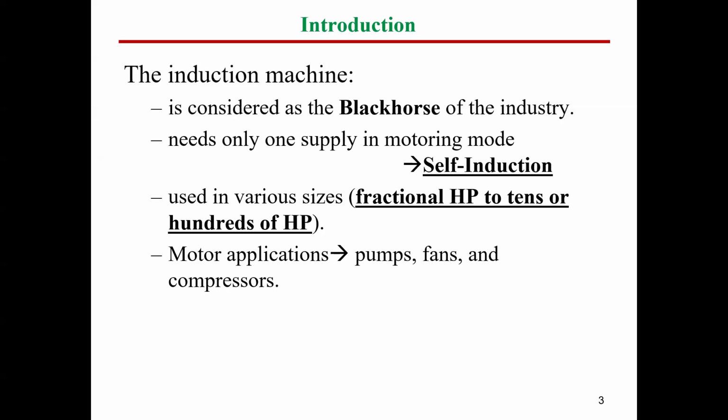So we will draw the torque speed characteristic and see the load and motor characteristic. For the fan load, all of these types of loads, guys, torque is proportional to the square of the speed. So this is one of the major load types used with induction motors.